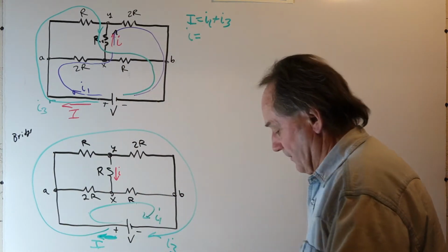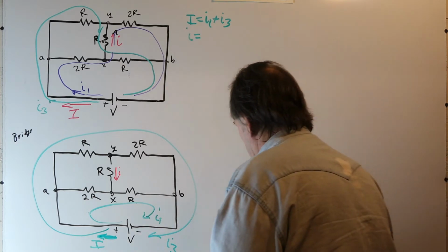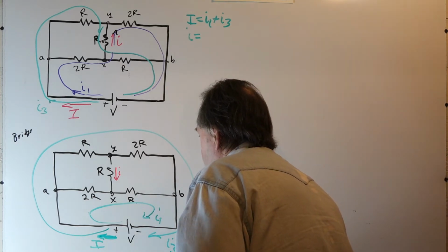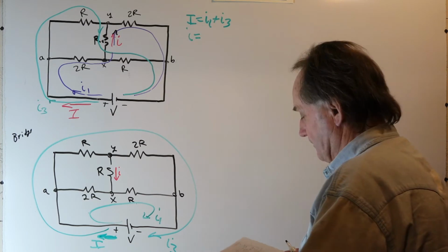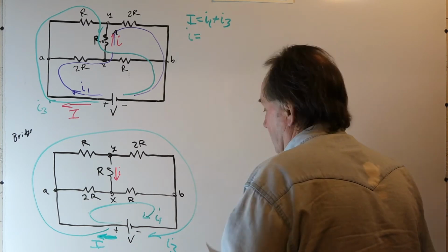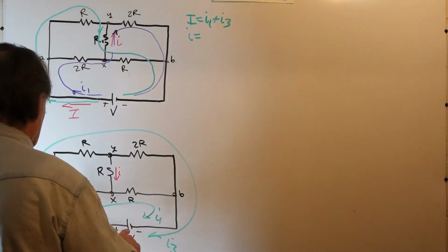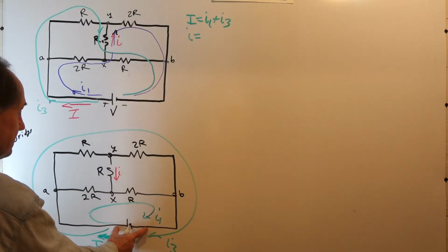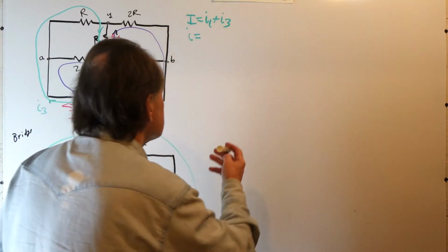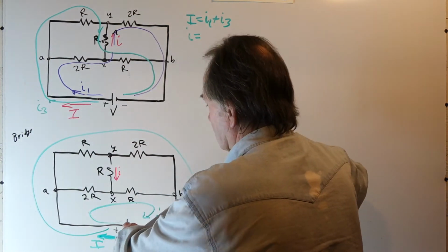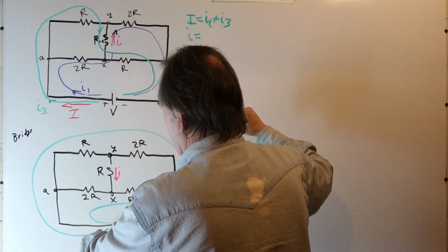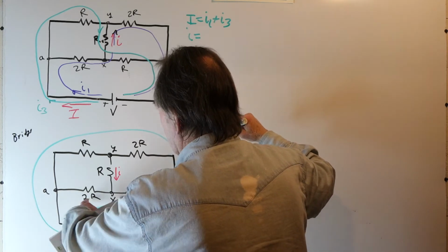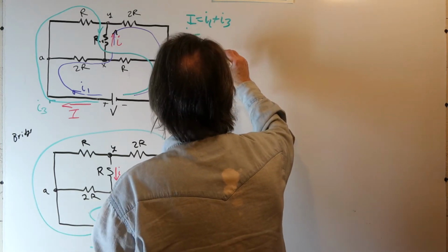Now what we do is, again, we'll use Kirchhoff's voltage law around loops and sum the voltages. By Kirchhoff's voltage law, we'll go first around the outer loop and then the inner loop. Since they both sum to V, we can equate the equations. So I'll just do that directly. Going around the inner loop, we have 2R with current I1 flowing through it.